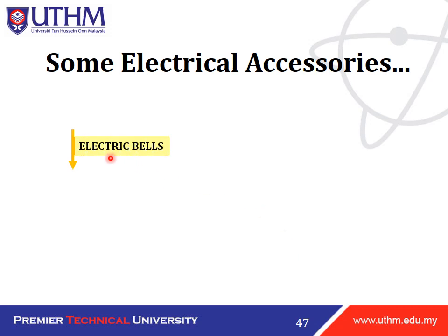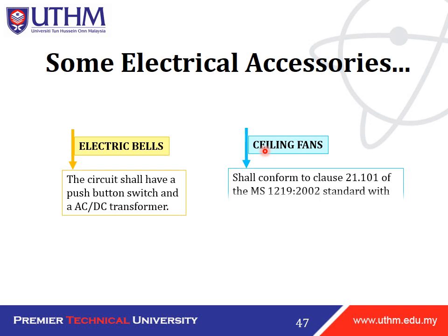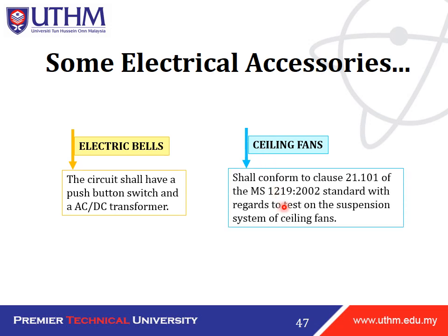Other electrical accessories include the electric bells. The circuit of electric bells shall have a push button switch and an AC-DC transformer. Other than that, we have ceiling fans. The ceiling fans shall conform to clause 21.101 of the MS 1219/2002 standard with regards to tests on the suspension system of the ceiling fans.